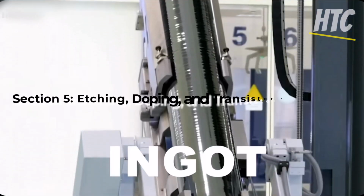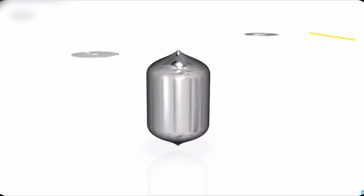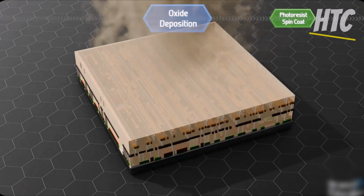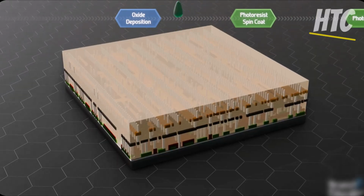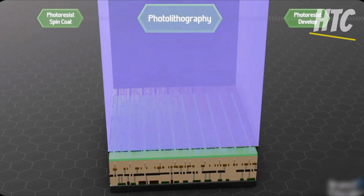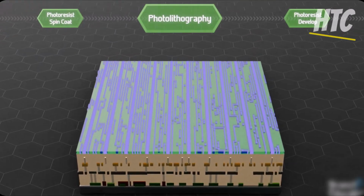Section 5. Etching, doping, and transistor formation. With the desired pattern now on the wafer, the next vital stages, etching, doping, and transistor formation, begin. In the etching process, chemical or plasma etching precisely removes unprotected silicon, sculpting the intricate pathways and features of the circuit. Simultaneously, the wafer is doped through ion implantation, where specific ions are driven into the silicon to adjust its electrical properties.